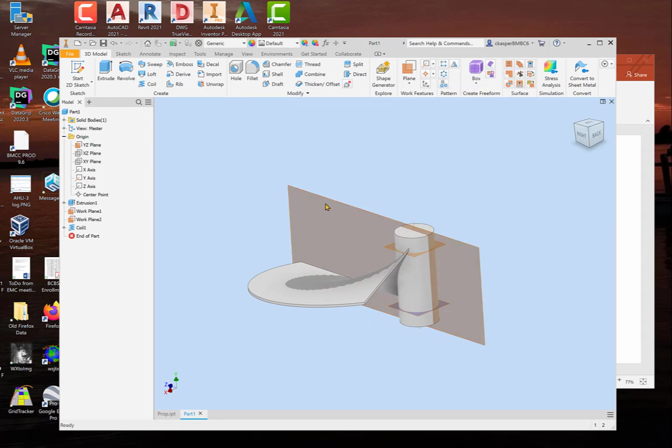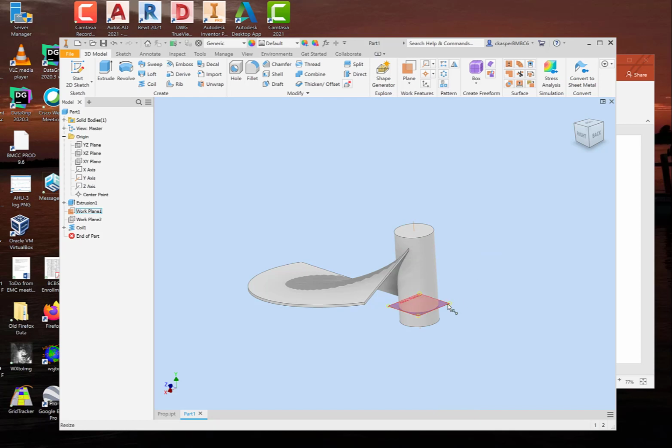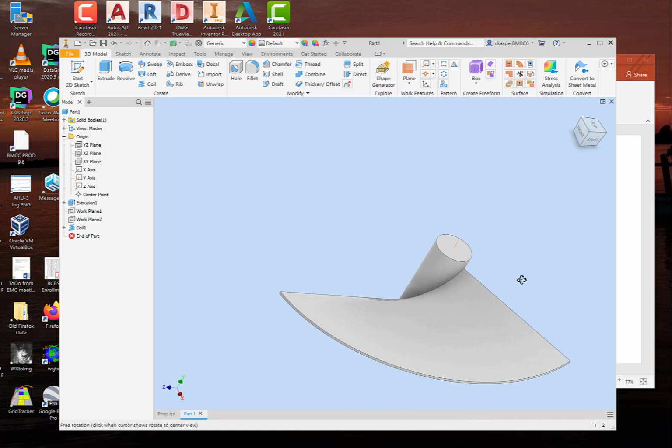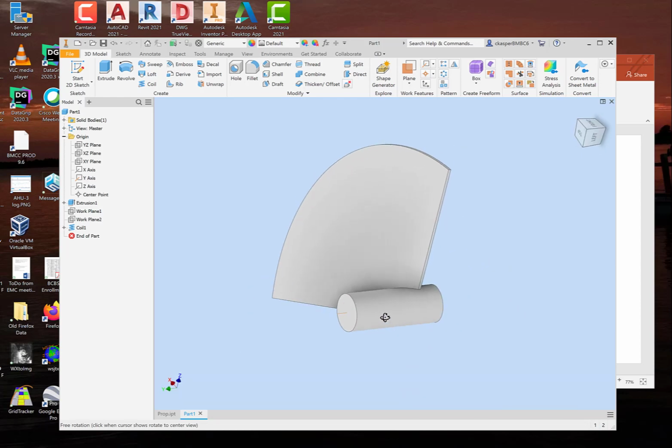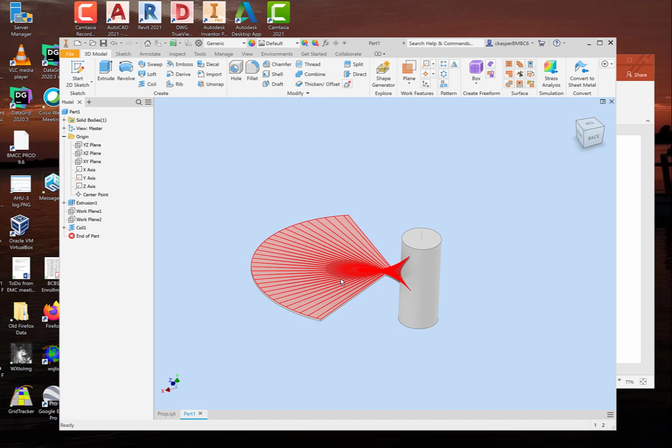So I'm just going to put my mouse on that edge, right click on it, and say visibility, which turns it off. I'm going to turn that plane off too. And why not? We don't really need this one anymore. So I'll turn its visibility off as well. I will keep the y-axis visible. There, isn't that easier to look at? Yeah, I love the shadows too. That's so cool. And you can see how it just kind of mathematically created this curve.